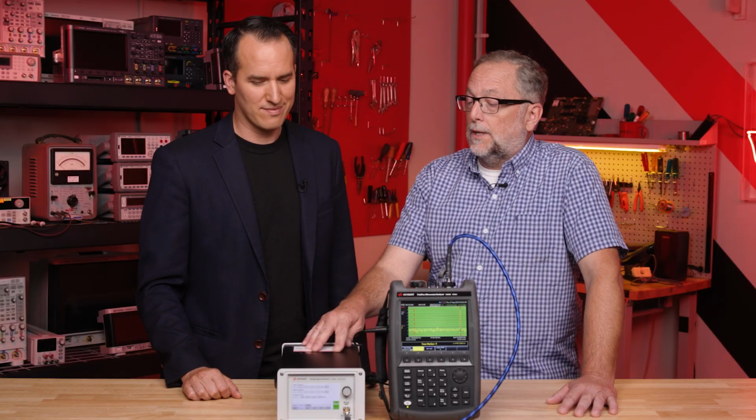Or if I'm doing filter testing and I'm sweeping through a bunch of frequency points through my filter, if I can do it that much more quickly, that means I finish my test more quickly. Again, these days time is money, so that's where this fast frequency switching can come into play. Another application, Daniel, is for radar test. Radars move quite quickly, and if we want to emulate a simple radar signal with something like this, we need it to be able to switch frequencies very quickly, which it can do.